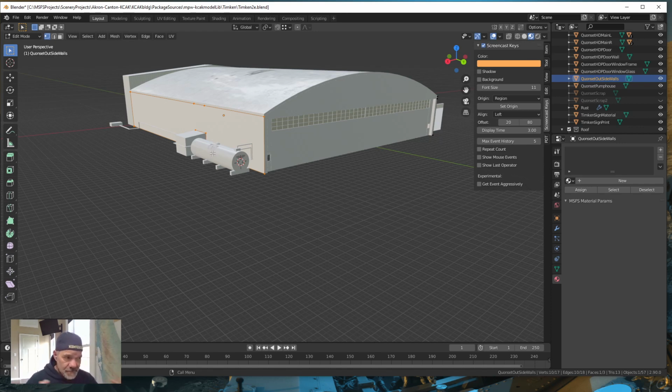However, there's another way to do it. If you were intending to do loop cuts later on, you can recreate this wall based on the edges and get rid of these and recreate it where these 2 vertices are no longer there. You can do that, and that would be deleting the faces but leaving the vertices.